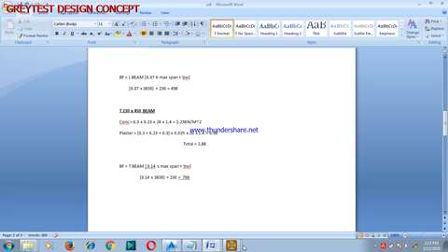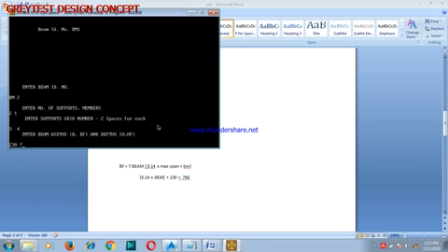And again, we've done the design of this slab already. You can go to that YouTube channel, which you are still going to get down below the description of this video. Now it is a T-beam 230 by 450, so we are going to use 766 for the sake of this class. The depth 450. Now HF, which is 150. Hope we understand this. Okay, press enter.